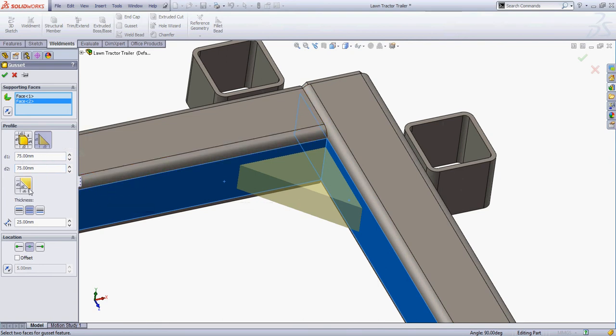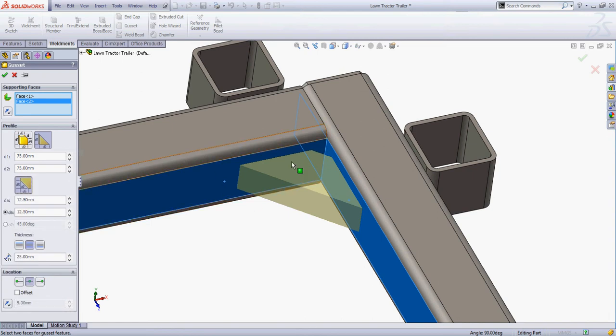The other thing I can do is I can add a chamfer. And what did we chamfer? Down here, and we typically do want that cut out because we need room for the welded bead that will go through here. And again, as soon as I add the chamfer button, I can set up its size. By default, it's 45 degrees. So again, I can set up the sizes for the chamfer. And I can make it unequal. I can deviate from 45 degrees if I wish.